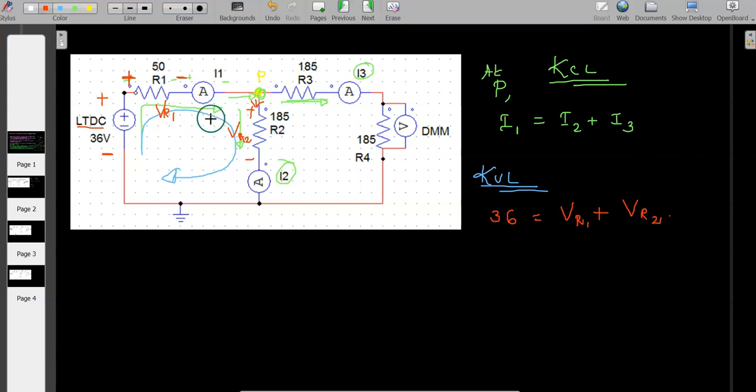So this is for this first loop. So this is your first loop. So considering the second loop, the second loop is considering for the same circuit. I am assuming the current flowing in this direction. So the drop polarity for this R3 is in this direction and the voltage drop let me write as VR3.